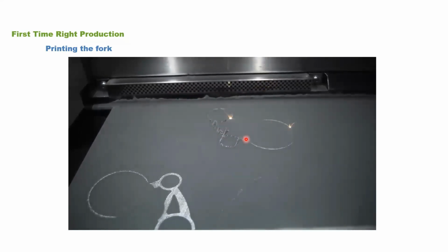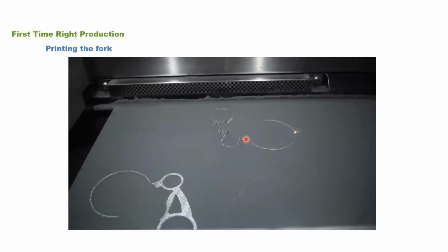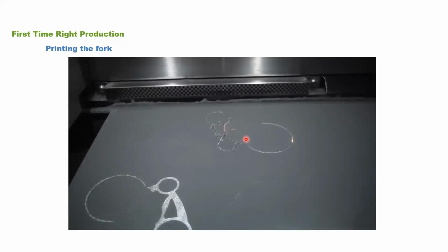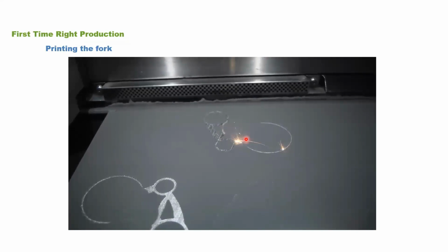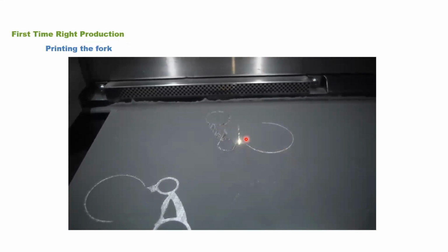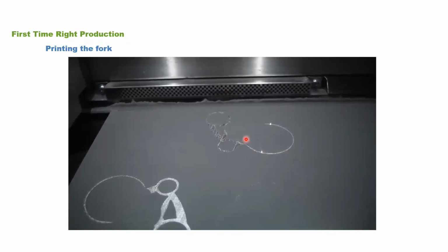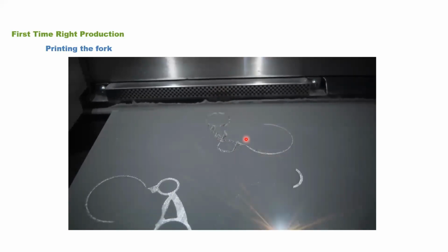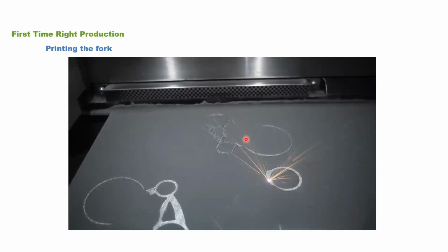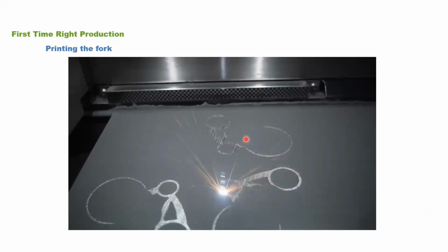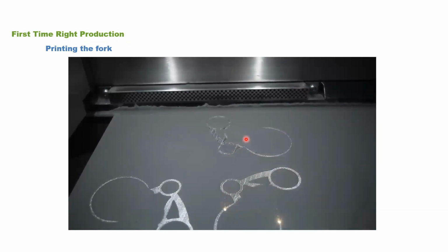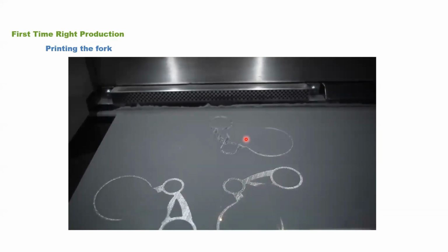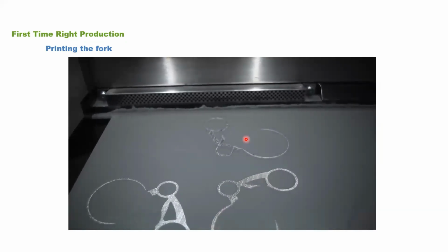And sometimes in different areas of the base plate, you might get different distortion because there are some inert gases used inside these chambers. Due to the gas flow, different regions might get different distortions, because the effects might be different. How to capture those kinds of things, we can use some calibration techniques. Yes, we can take those effects into consideration.